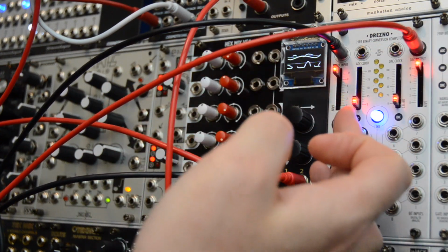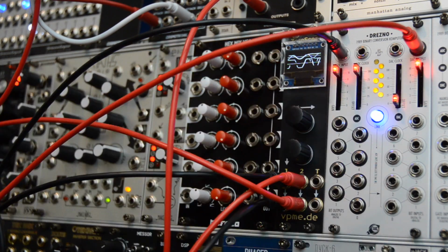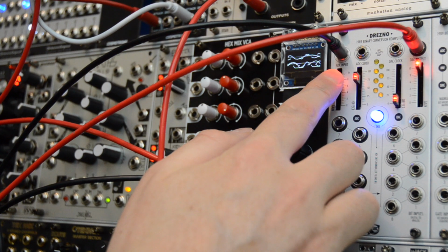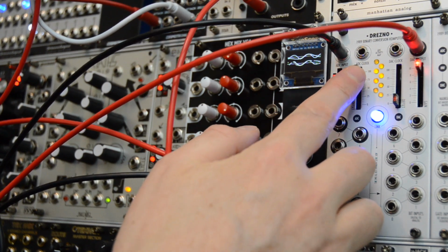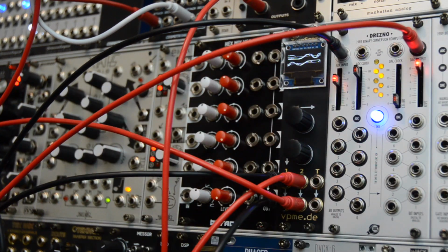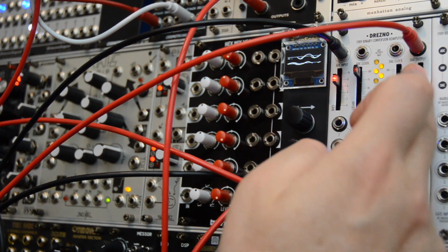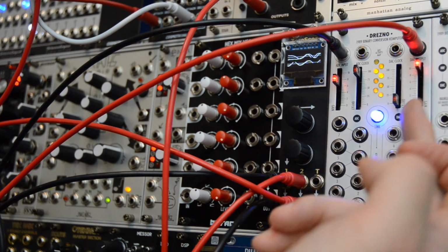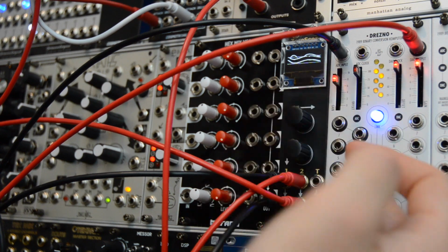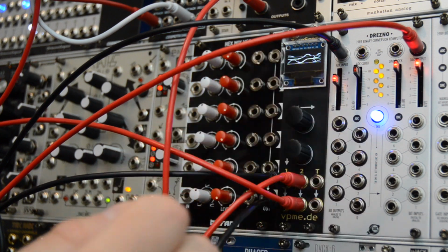Now to solve this, you might think turning up the offset is a good idea. But as you can see now, the wave is clipping on the top as well. What you need to do is fine-tune the gain and the offset sliders to get the input and the output signal to be almost the same. Turning down the gain in the output just attenuates the signal of the output, and turning up the offset actually in this case offsets the wave completely above 0 but also clips it.